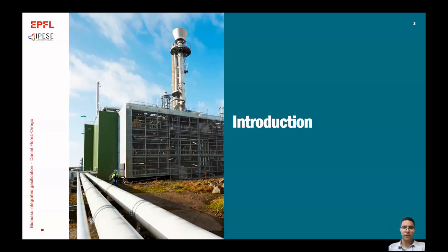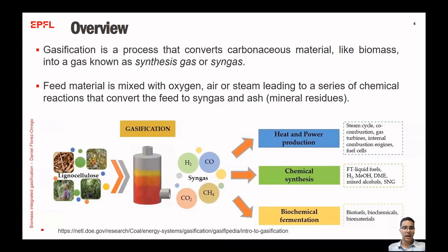Let's start by introducing the gasification process as a thermochemical process that converts carbonaceous material, such as biomass, into a gas that we know as synthesis gas, or in its shortened version, syngas. The feed material is mixed with oxygen, air, or steam, which we call gasifying agents, leading to a series of chemical reactions that convert this feedstock into syngas and ashes that are the mineral residues.